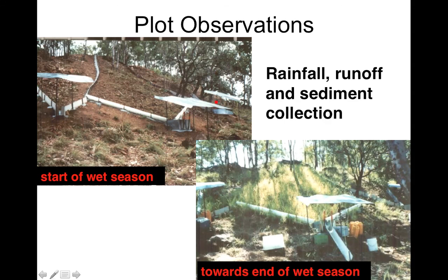And these are other types of observation plots. These are in natural sites, I think up in the Northern Territory. So we have some catchments up here, which are bounded. And at the bottom here, here's a small little subcatchment, and here's another little subcatchment. And they've got some guttering on the sides to make sure that we know the area over which the flow's happening. And at the bottom here, we've got some runoff troughs, flumes, which are measuring the flow rate.